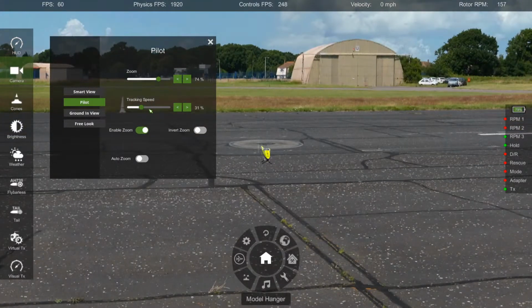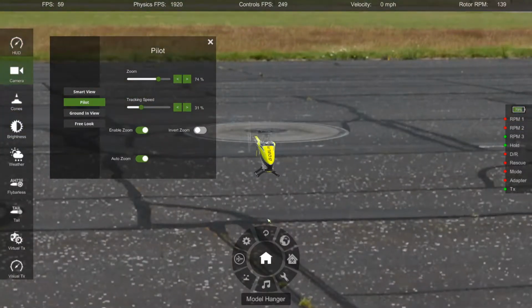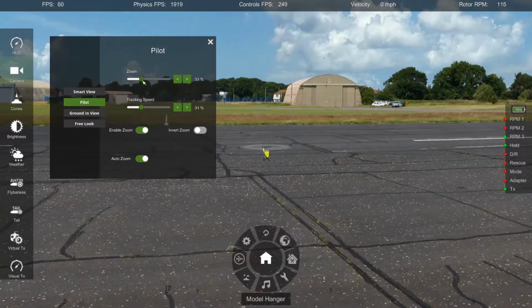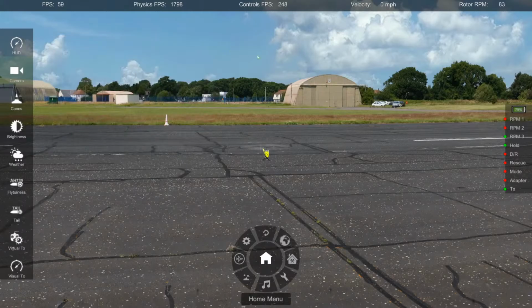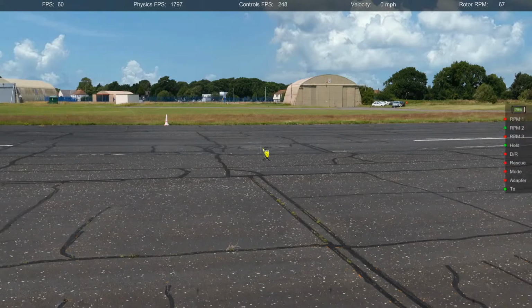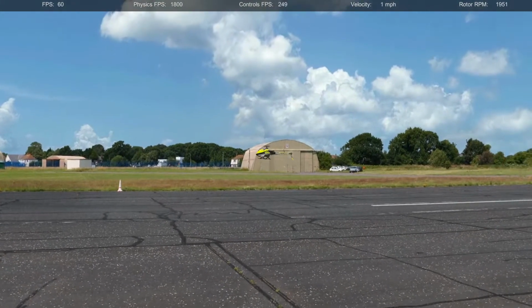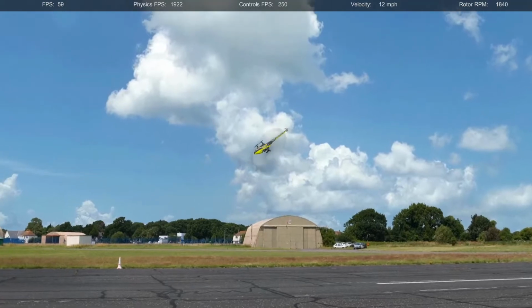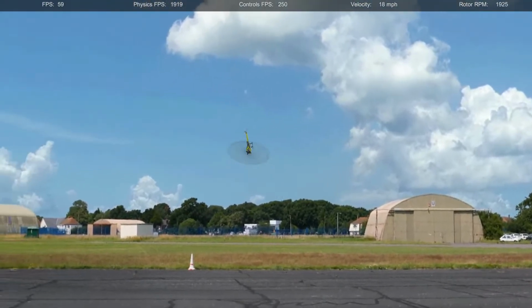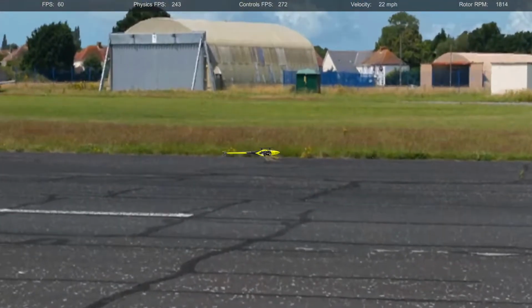That's Prandtl's 1933 paper on what the upwash should be. And the blue line that humps over the top and then goes out to the right, that was the data that I calculated with my interns on what the upwash was outside of the wingtip. And you'll notice that when you lay that over the top of the bird data, all of a sudden everything lines up. The birds know exactly where the best upwash is.